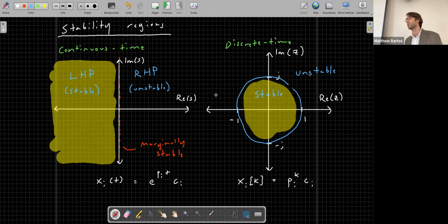In particular, when you're doing CFD solvers, computational fluid dynamics solvers, hydraulic solvers, some of you work in contaminant transport, you need to ensure that the poles of your system, or eigenvalues, if you have a system of equations, lie inside the unit circle. So that notion of stability is the exact same kind that I'm talking about here. So if you have ever worked with the CFL conditions, those are equivalent to the conditions I'm showing here.